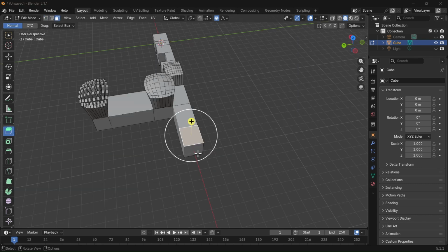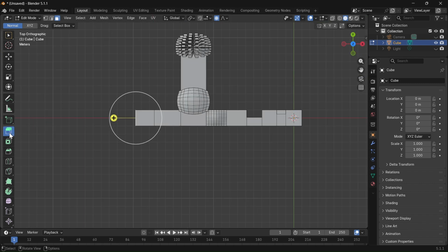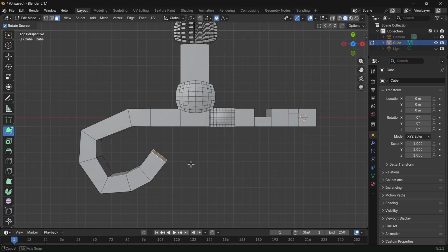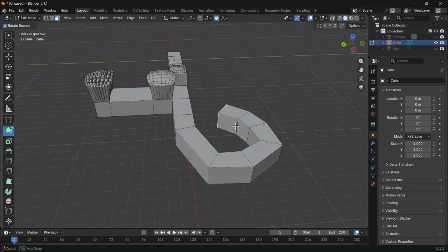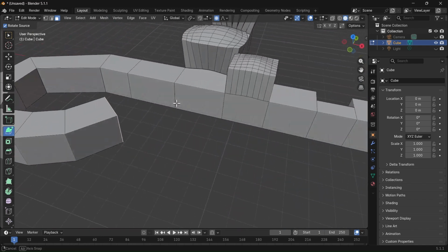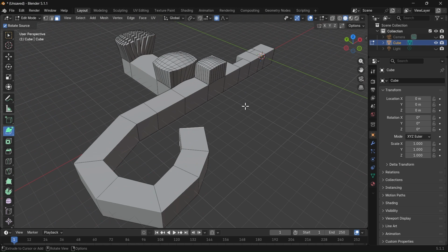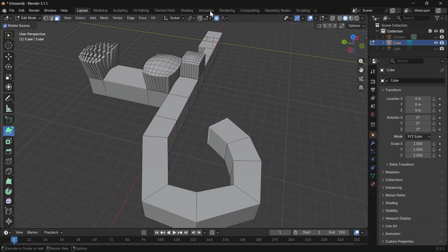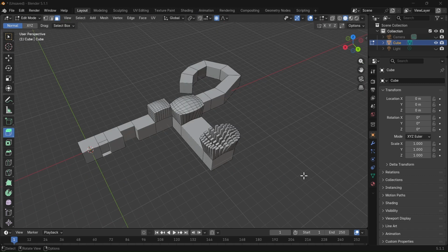First of all, let's select a face. Let's select this one and go to extrude to cursor and then press. We are seeing that it is extruding the geometry to my cursor like this one. This option is actually fascinating, but I find it less useful as it has less control over exact locations. Now let's use our learnings and make a practical example.